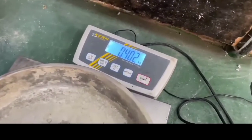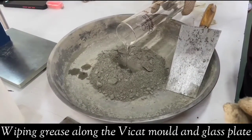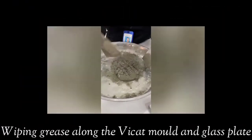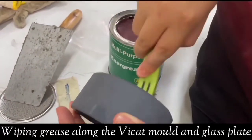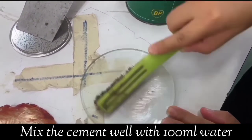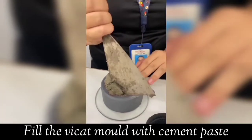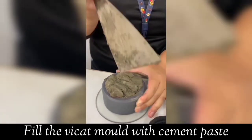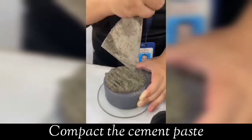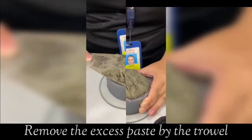First, 400 gram of cement was weighed on the weighing balance. Then 100 ml of water was added to the cement and mixed well for 3 until 5 minutes. Grease is wiped inside the VICAT mold and on the glass plate to avoid the cement from sticking inside the VICAT mold and on the glass plate for a long time. The VICAT mold is filled with cement paste, which is placed on the glass plate. Ensure to compact the paste well after filling the mold. Fill the cement paste to the top of the mold. The excess paste was removed by the trowel.